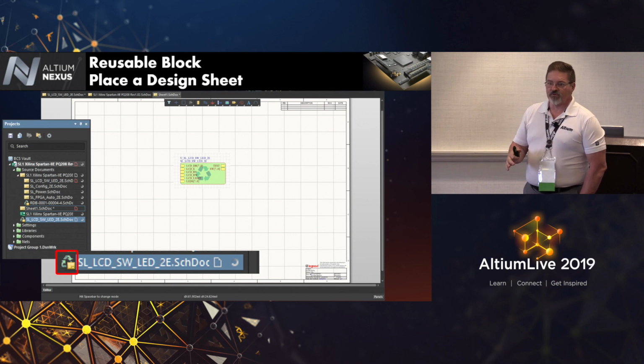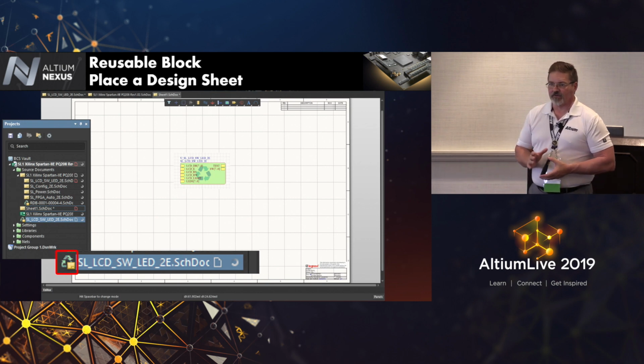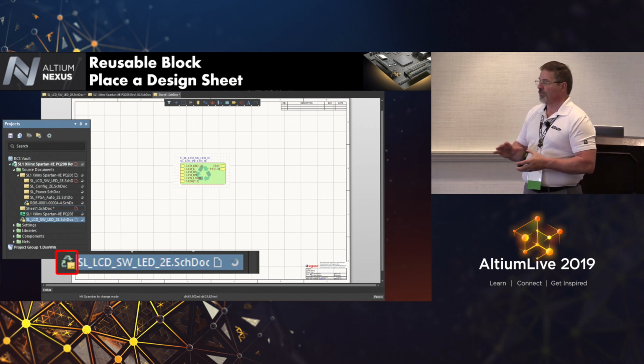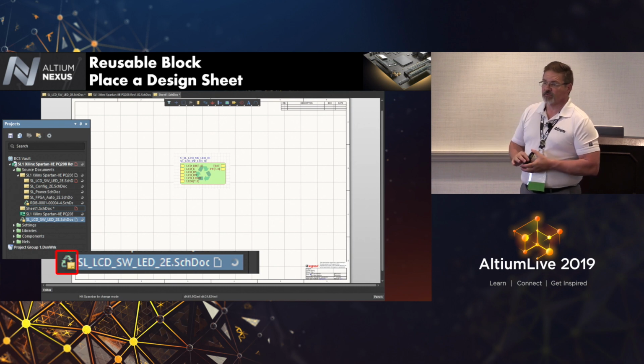Because it's already gone through UL approval, we simply lay down that PCB layout as we did it the first time it got through UL, and we're done. About 99.5% of our projects that we send through UL get through first time. So we just slam dunk them through there.